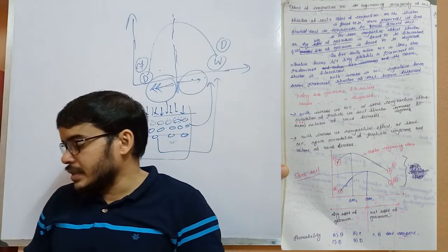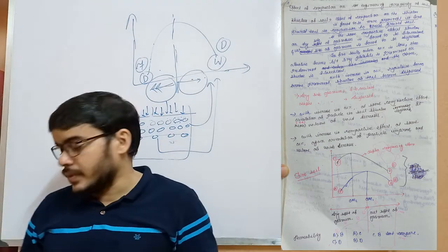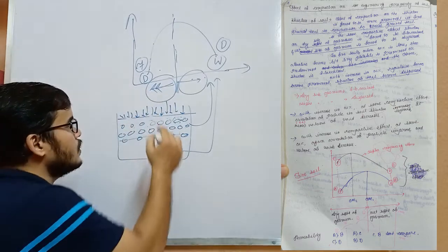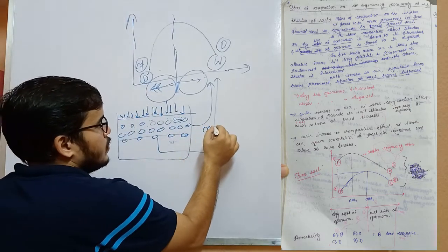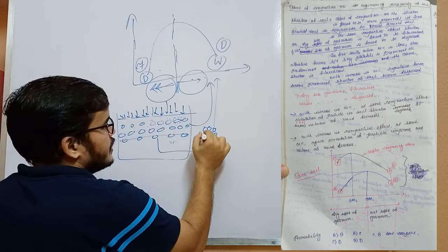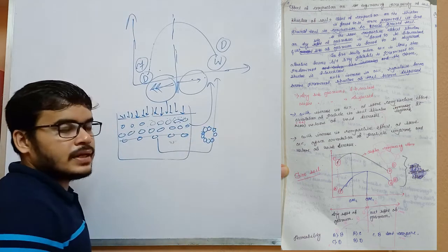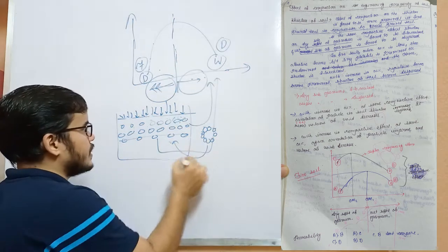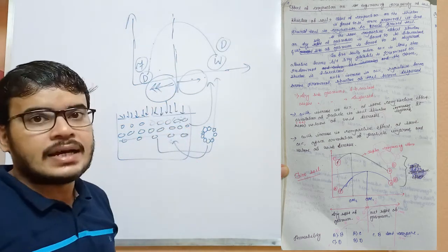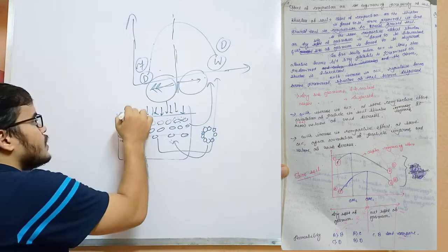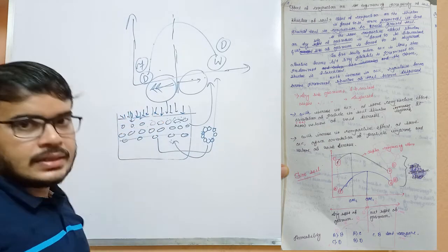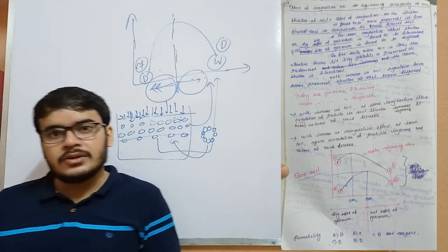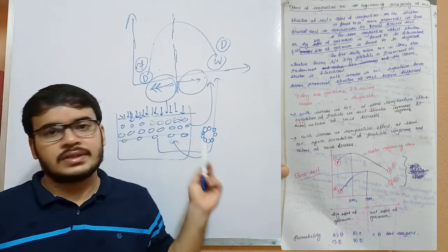And now check two notes. With increase in the water content, the volume will decrease, as due to the increase in the water content, this flocculent shape of the solid particles will break and they will be dispersed, and in that case the volume will decrease, as we know that the soil will be compacted more densely in comparison to the flocculent structure.